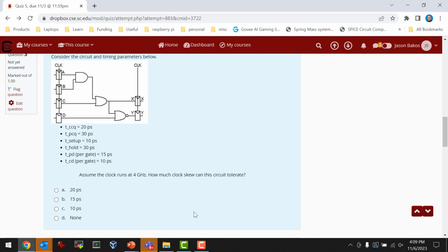So this is a delay skew. And this over here is a head start skew, because you have to consider that the skew may delay you in the case of setup time, but it may give you a head start in the case of hold time. So you have to consider the worst case scenario with the skew, because the skew is a plus or minus difference in clock phases. So this is 30 picoseconds